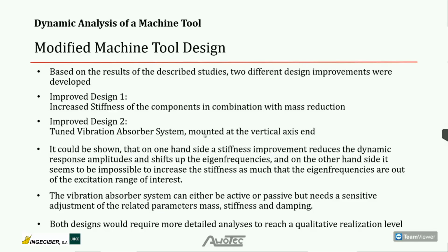But it is not possible to eliminate all eigenfrequencies out of a range of excitation, because this machine would be so stiff that it can't be built.